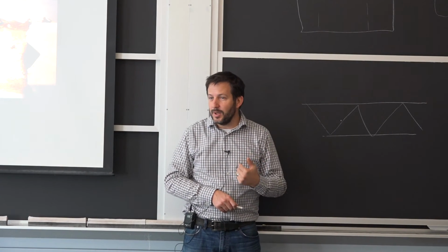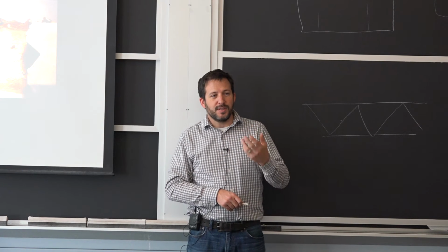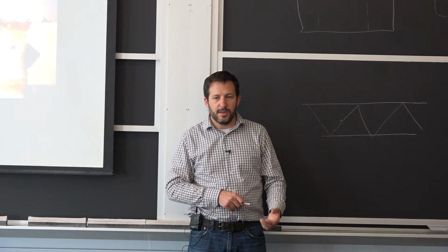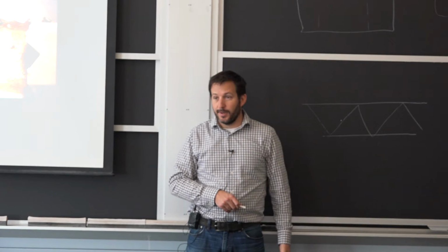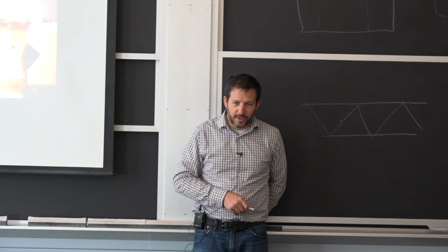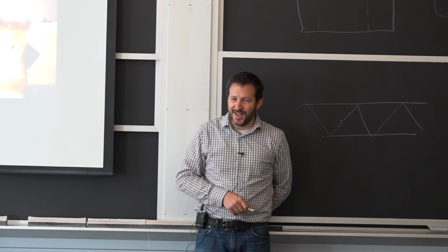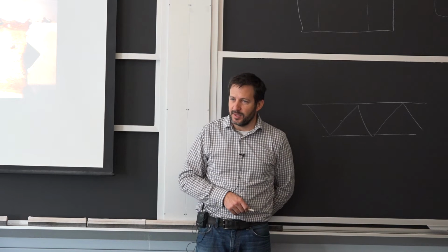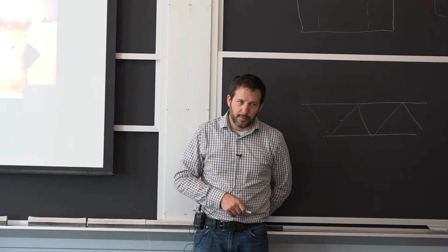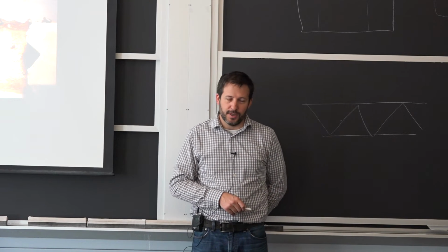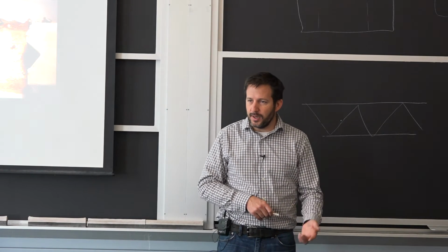The way the code is built for the fabrication of these joists does have provision for quality control of the welds and making sure it's inspected and tested, but it's not done as much as it would be for a pipeline, for example. And we can all decide whether that's acceptable or not. It's something that the buyers ultimately have to say: do I want the standard of care, or do I want something better? And if I do, then there are these third-party inspections.